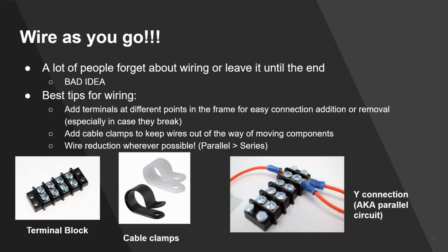It also helps in labeling, because the more terminal blocks you have, if you're labeling your wires with little pieces of tape at the beginnings and end of each wire, you know exactly what they're for. And the more of those you have, the easier it is. If something goes wrong in your motor function, you can trace it back way more easily if you have more terminal blocks, because you can test the current or the voltage that's being delivered at each part of each terminal block, and then you can determine where the problem is to see if there's a connectivity issue.